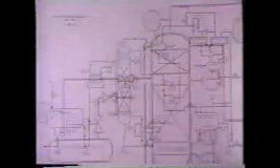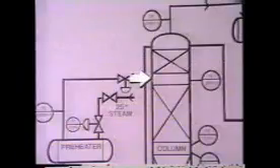The column's bottom temperature and pressure will indicate the right time to begin bottoms takeoff. Therefore, the inside operator will monitor both. To begin bottoms takeoff, the inside operator sets the bottoms takeoff flow controller to a flow rate specified in the system operating guidelines. Now that there is a steady flow of product out of the column, the column has to be fed continuously. Once continuous feed begins, the feed preheater is started up.